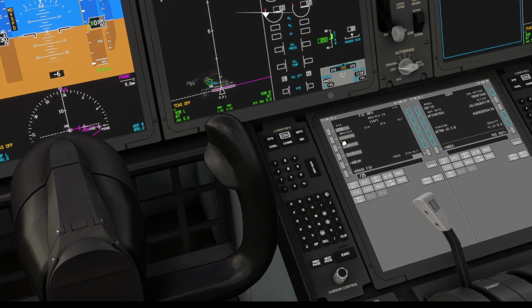25 miles as a reference. And usually via route 2 is where I would set up our engine failure procedure, which is most likely gonna be straight ahead and climbing above the MSA and staying within 25 miles, which is basically the circle of the MSA. And then you would be safe. So that is usually what I would set up on route 2, but it's not working on this version.